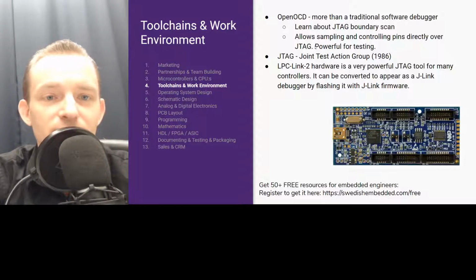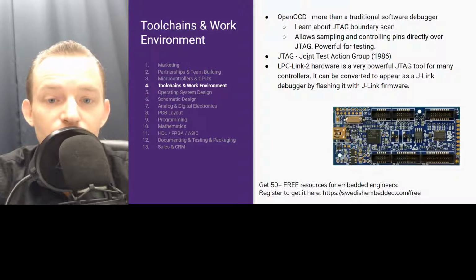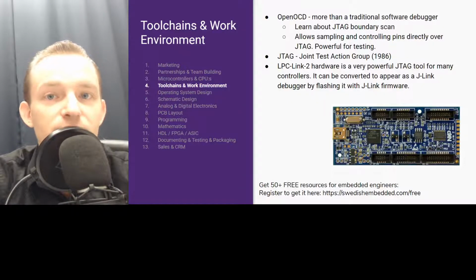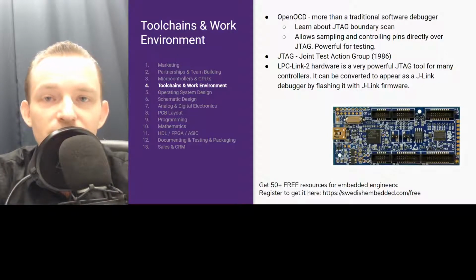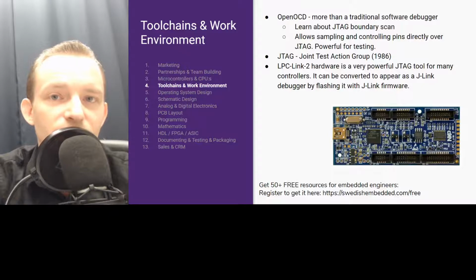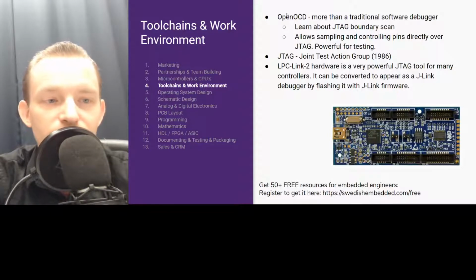With OpenOCD, JTAG stands for Joint Test Action Group. And one of the features of JTAG is that you can analyze pins on a chip. You can actually read out states of pins without having to go through software. So you can, for example, connect the chip through JTAG to your computer, and then you can look at the states of the pins. And the software can be running while you do that. But you can read out different types of information that is helpful for debugging the circuit board.